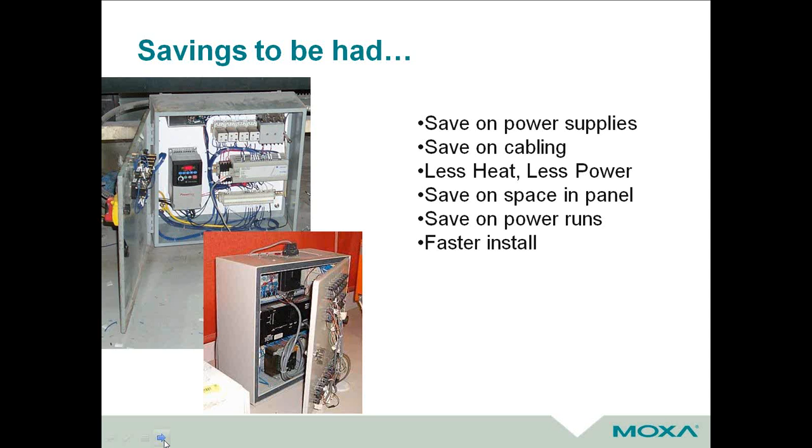Why would you want to hire an electrician to go onto your factory floor, run a conduit for 220 or a 110 just to put it into a power supply that converts it back down to a 24, 48 volt DC just to power an Ethernet switch? A lot of times excuses have been, I don't want to put a network in because I have to run conduit, hire a contractor. It's going to be way too expensive, just the logistics. So with PoE, you can get around that. And of course, it is much faster. You plug it in, your device turns on, and just starts working. That's probably the most fantastic piece of it.